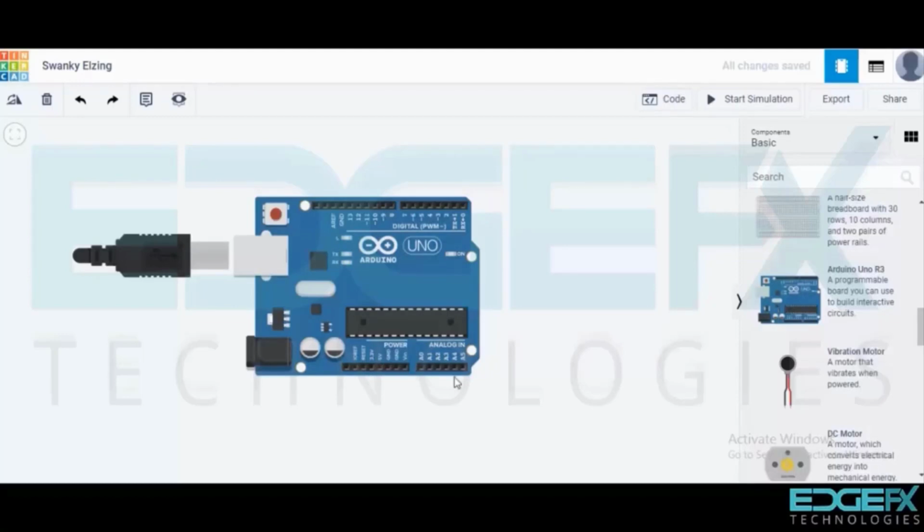Here we have a couple of LEDs. These are the LEDs for TX, RX, indicating transmitting and reception, and here are the respective TX and RX pins for serial communication with external modules. Here we have an inbuilt LED connected to the D13 pin by default.